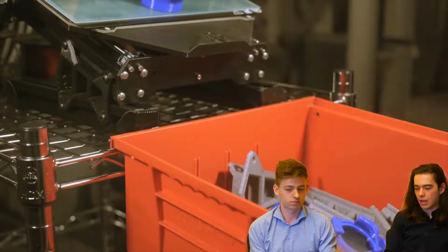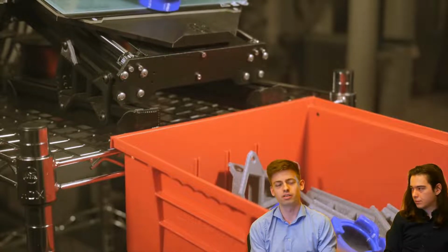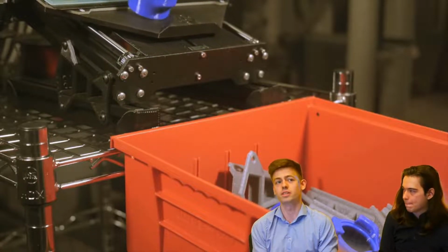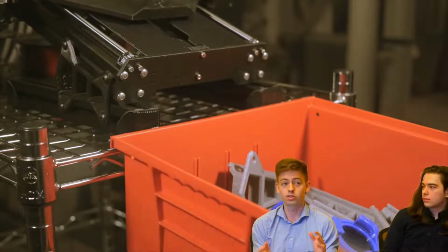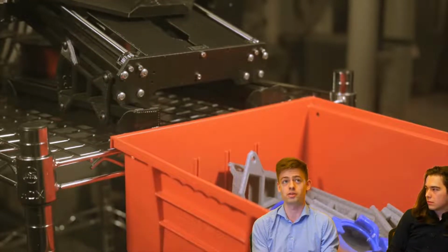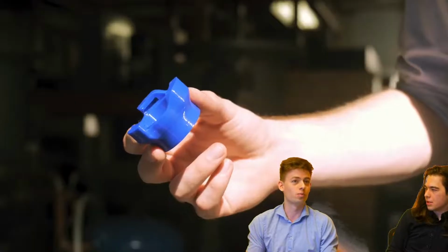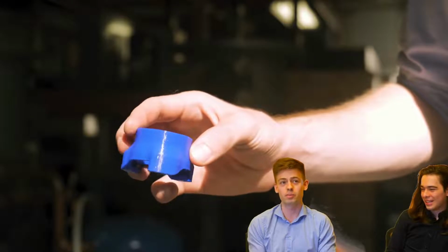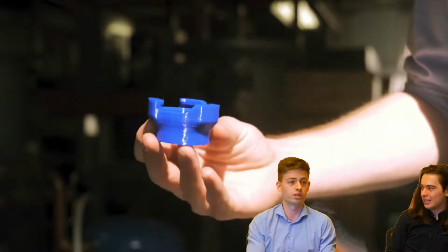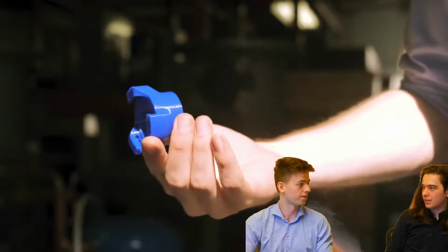It's actually got me thinking of different offsets you could have. Because with retraction, you could have Bowden and direct drive use the same G-code if you use firmware retraction. I don't know what G-code it is, but you just send a G-code to the printer and it knows to retract by the amount that it retracts.